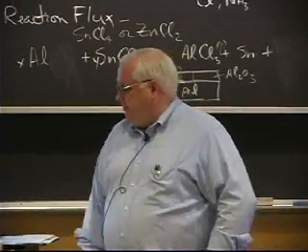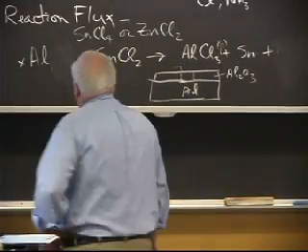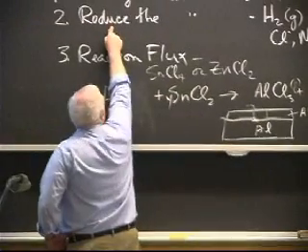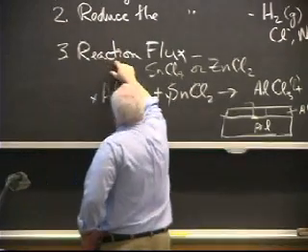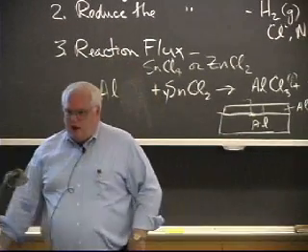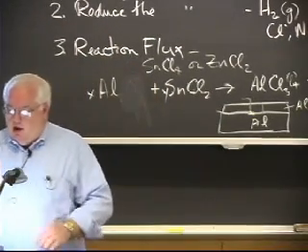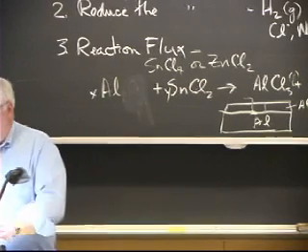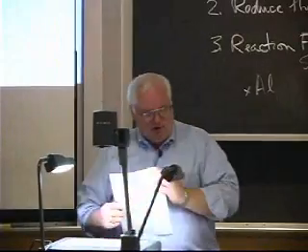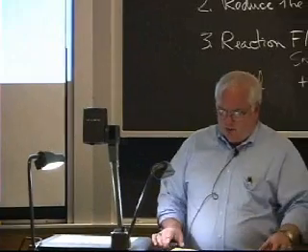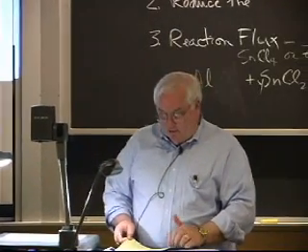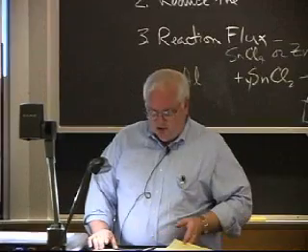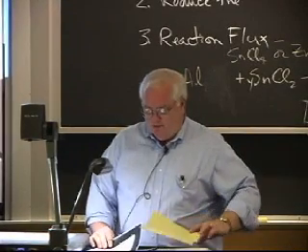But they are used. And unfortunately, they call it a reaction flux. This is also a reaction, but it's not a reaction with the contaminant. It's a reaction with the base material. And it turns out no one's ever found anything that would do the same thing with beryllium and titanium, and so they're basically unsolderable. In fact, they're not even very brazeable. Well, at very high temperatures they're brazeable, but not at the lower temperatures.